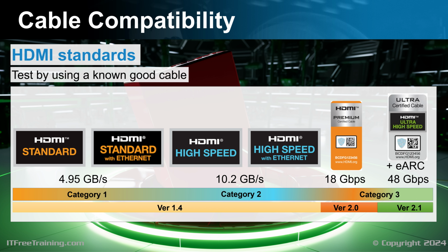Generally, the best cable to test a monitor with is the cable that came with the monitor, if it's available. Unfortunately, there are a lot of cheap cables on the market, and often you won't be able to tell what the cable supports by looking at it. Don't assume, test the cable to make sure that it's working and that it supports the resolution that you're trying to use.